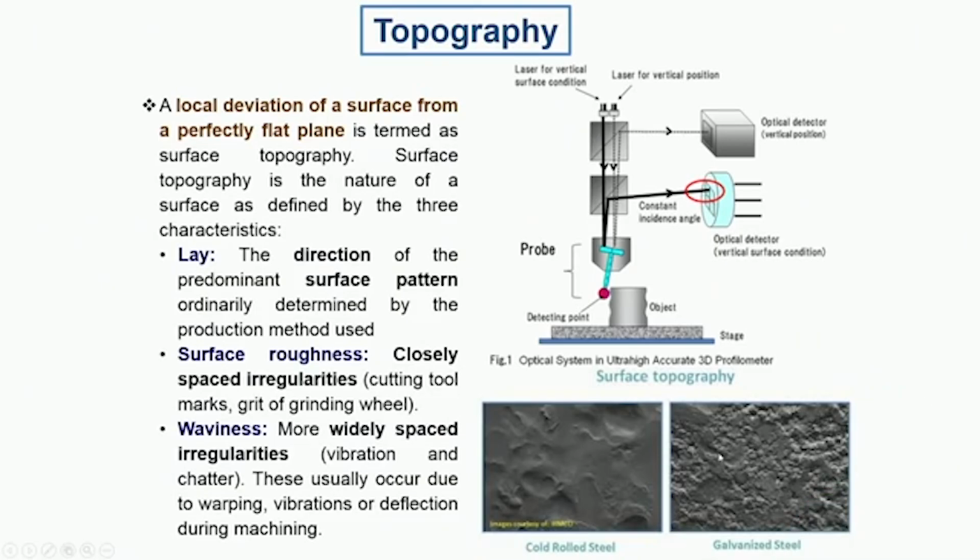On the other hand, the steel sheets which are coated with zinc and applied for car bodies and various other applications, or even painted on top of that, will also have certain roughnesses, and the typical amplitude of these roughnesses could again be a few micrometers, if not more.